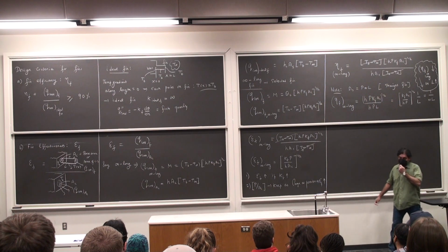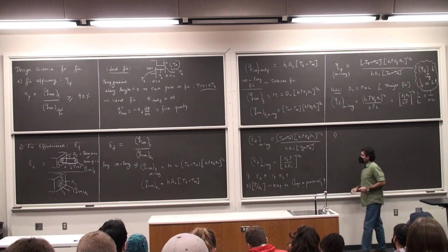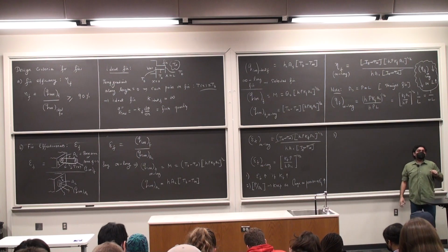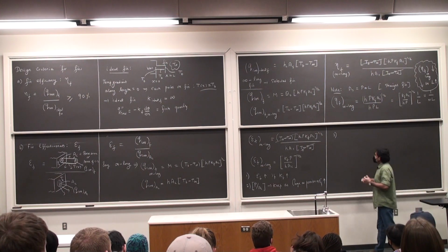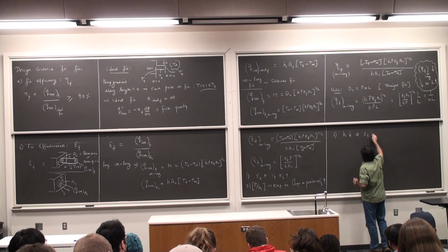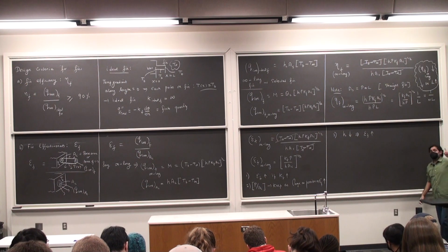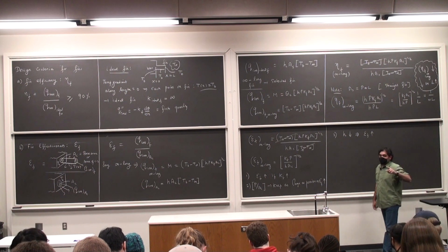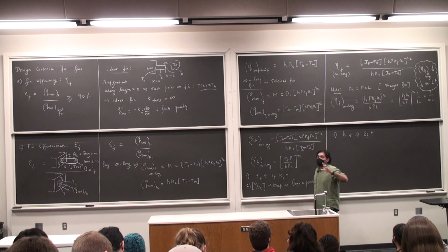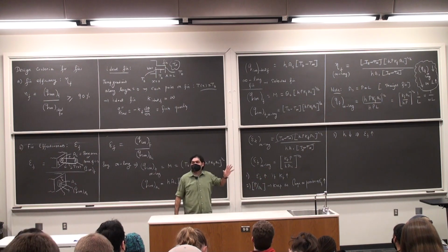The third thing, which we don't control but we could perhaps play around with, is the convection coefficient. I can't change it, but I can do some things. So H should be low, which implies effectiveness is high. So when you use fins for cooling, the question typically is, do you place the fin on the fluid side, the liquid side, or on the gas side?